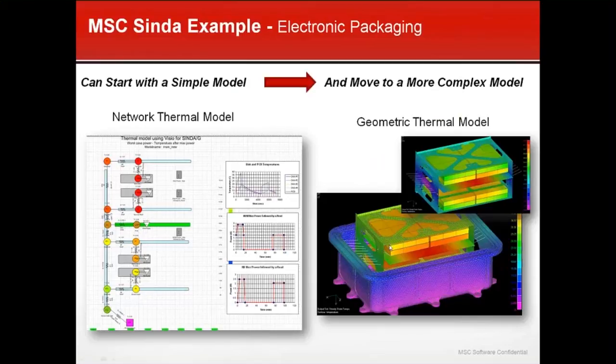But here was the actual hardware, and it was an enclosure here that was hermetically sealed and filled with nitrogen, and inside it had some hard disk, and this went up on a spacecraft. And these hard disks, we had to get the power out of this little frame here through some stainless steel rope isolators, and I was concerned about that heat transfer path because this was shock isolated, so I kind of cut this in half and built 1/2 here just to see if I could get that heat out through those 10 coils in that stainless steel rope isolator, and I saw that I was going to have problems, so I ended up adding at the bottom here some flexible copper braided straps and sized those straps all in this model,